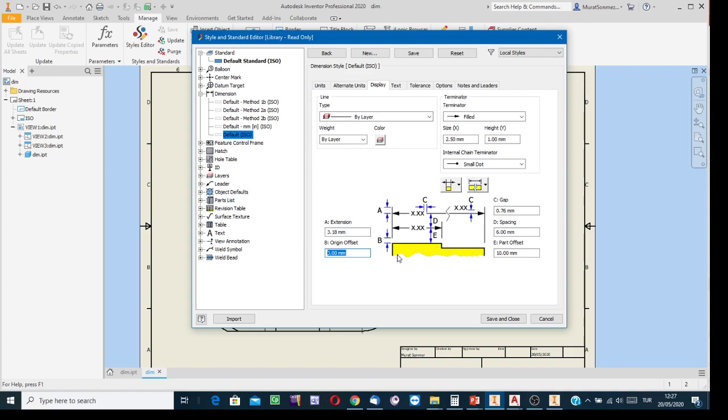This yellowish one corresponds to a part of a certain orthographic projection, and for this part, the dimensions are to be shown. Distance p is the space to leave at the beginning of the extension line. Certainly not 0, but maybe 2-3 millimeters. For this example, 2 millimeters is suitable. Extension lines are further extended beyond the termination symbol of dimensioning lines. How much? 2-3 millimeters.